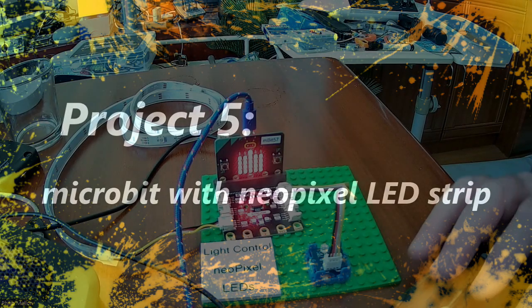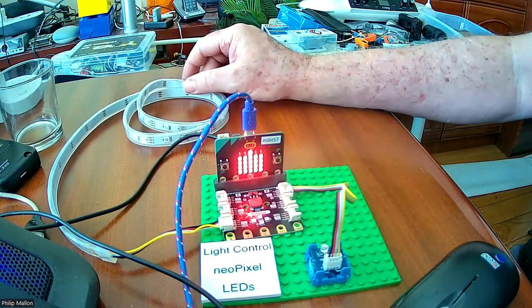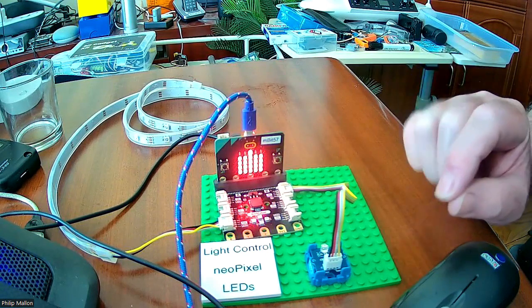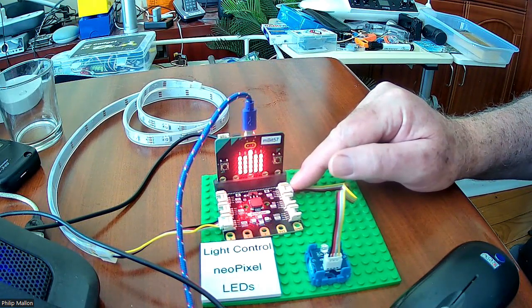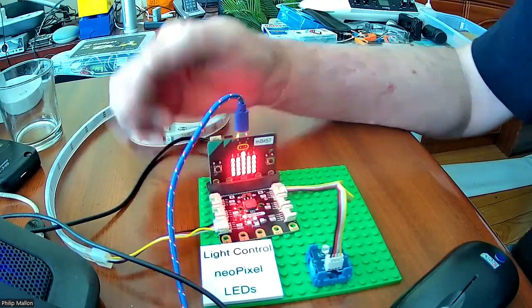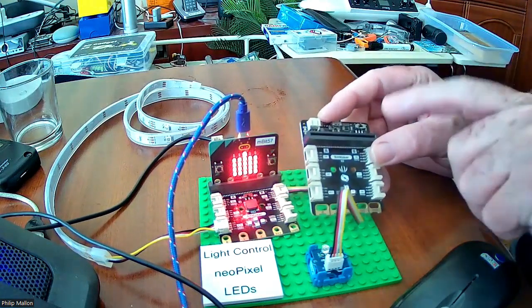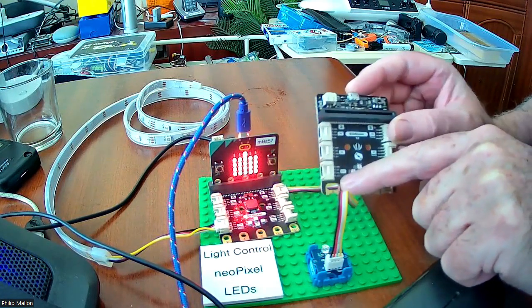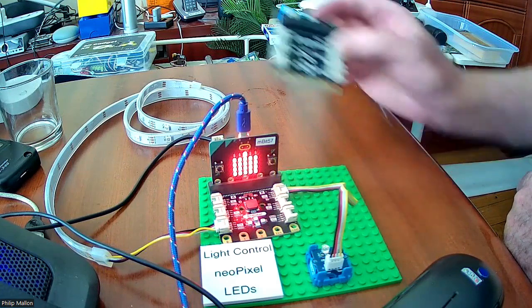Now we have Project 5, and we're using the neopixel strip, which is in the BitGadget kit. And what we're going to do is turn on the LED when it's low light. So we have a light sensor, similar to Project 5, going into port 0, and we've got the neopixel array going into port 16. Now, be a bit careful. If you've got version 2 of the BitMaker, they've swapped port 15 and port 16. And it took me a while to work that out, but that was a bit of an issue with the quality control from Seeed Studio.